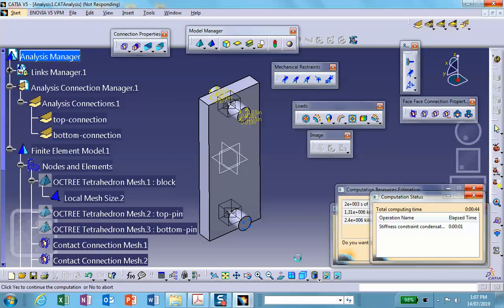Look at this, by the way. Inadvertently, I may have selected quadratic element, and this is a gigantic number. It will run, but you can see that the time, CPU time, is 2,000 seconds. So, oh my God, this may take a while. I may have to kill this and actually change element type.